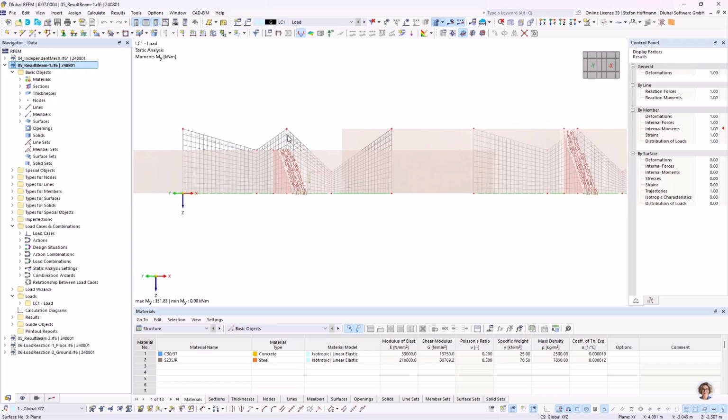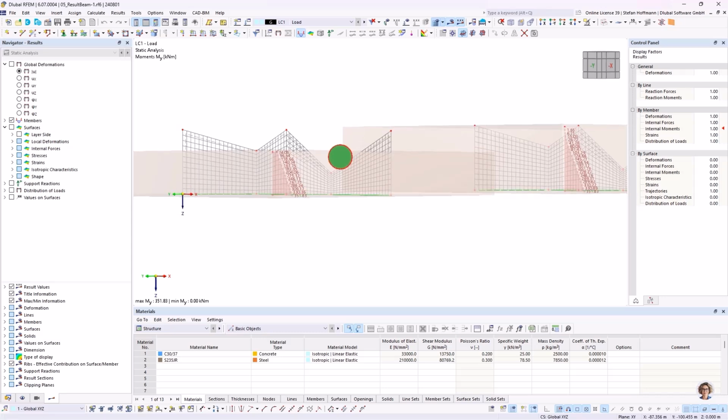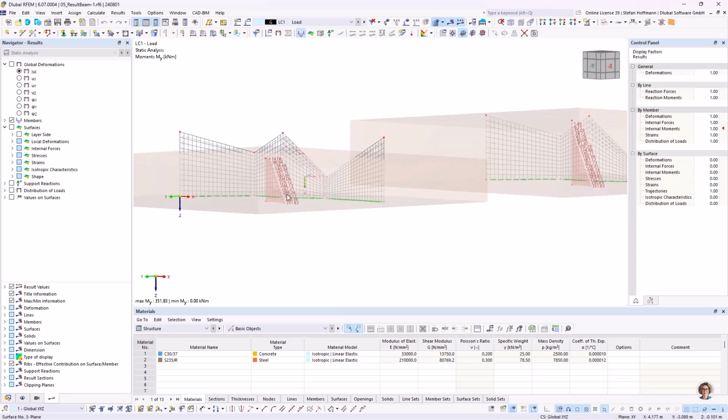On the left, the beam is not going to the top of all surfaces, and on the right, the beam is going to the top of all surfaces. Which forces can be integrated? It's of course only the forces in the effective area of the result beam. So if it's not long enough, you can see that the normal force, which is summed up from top to bottom, will not start with 0, but on the right it is 0.